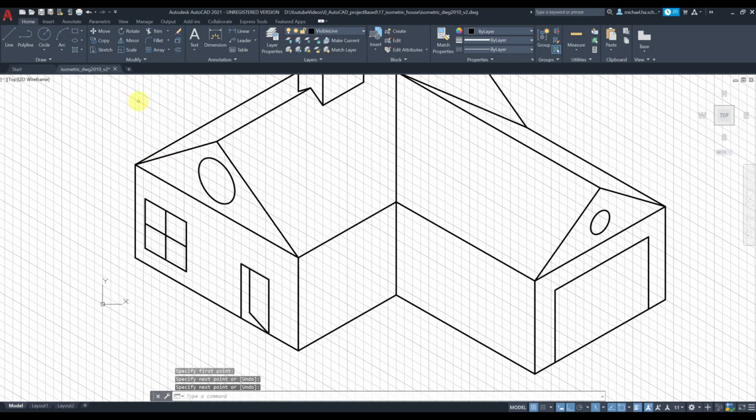You can go ahead and draw isocircle with ellipse. Press I for isocircle, center, and there. Again, another one. I for isocircle, center, there. Let's go ahead and trim.